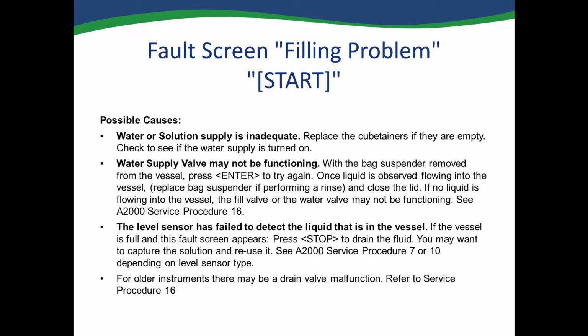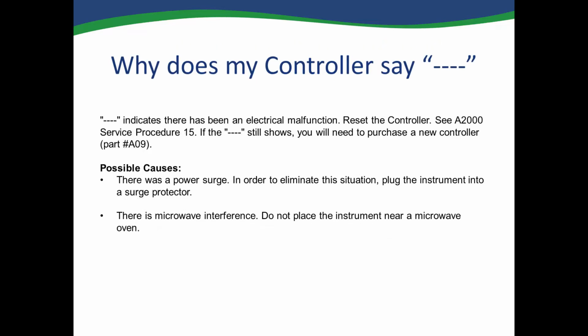There is no reason to restart your instrument. If your controller comes up and you see 4 dashes on it, typically this means you had a power surge or your controller is corroded. You can try to slide your controller out of the instrument by simply grabbing the controller and sliding out of its housing. Sometimes sliding the controller in and out will resolve the problem. If you did have a power surge, typically you will need to replace your controller.